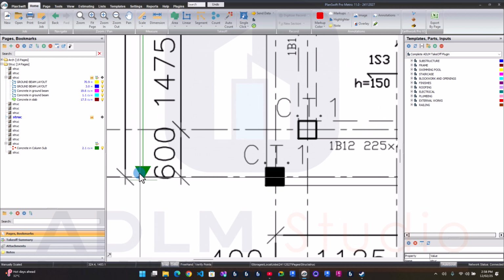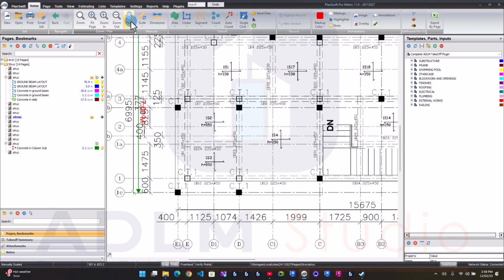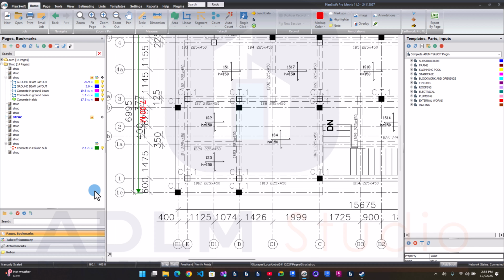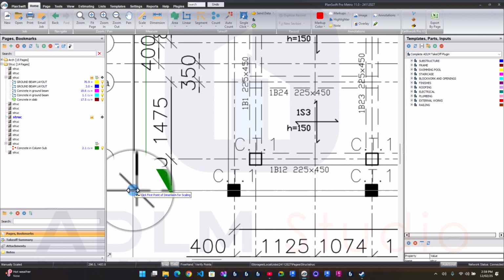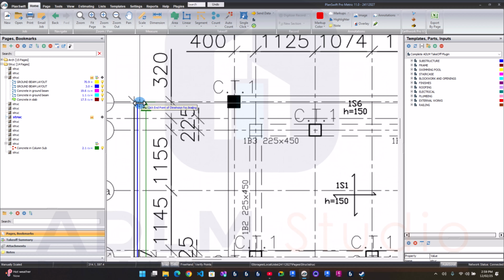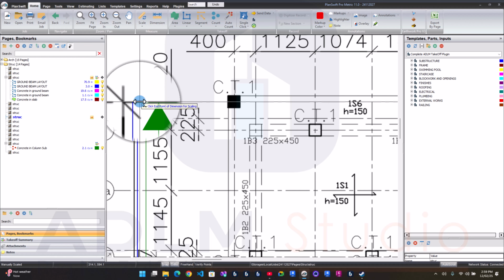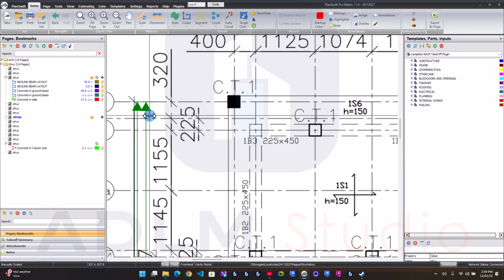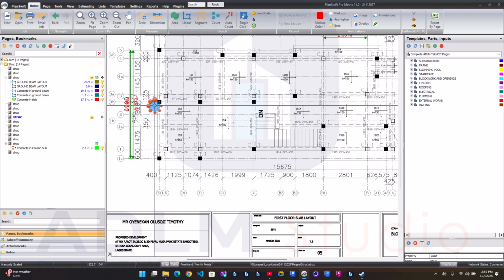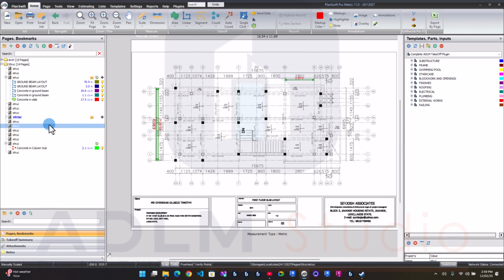There's a small error. These are errors that are possible during scaling, so I have to rescale that page. I click on scale, and I'll name it 6.995. I can press M on my keyboard to magnify. So M to magnify, and I'll pick from that point, then to the top here. Okay, good. Now you see your scale is correct. So that's for the first floor slab.